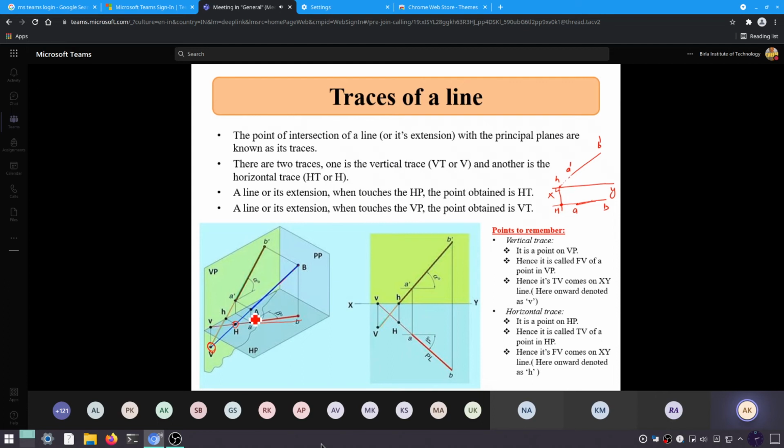So we can say that phi line will pass through this line, true line we are talking about, and so we are going to use that information only. Okay. So the blue line, if it is making 40 degree with VP, so this angle should be 40 degree. Okay. Whatever the angle we are going to make it with XY line, so we'll get the same line over here. So XY line is parallel somewhere here, so we'll get the same inclination over here.